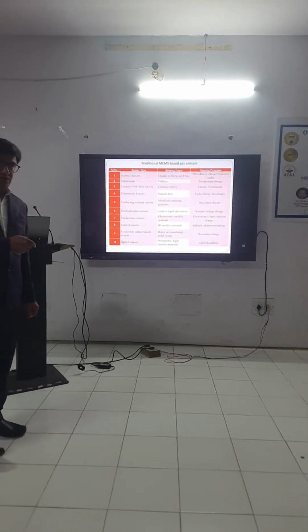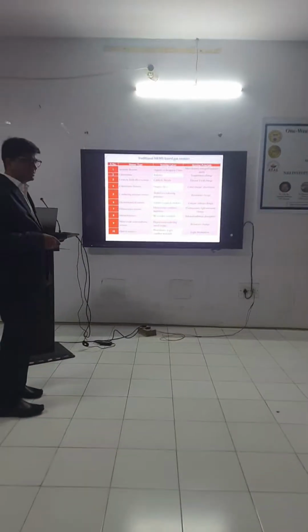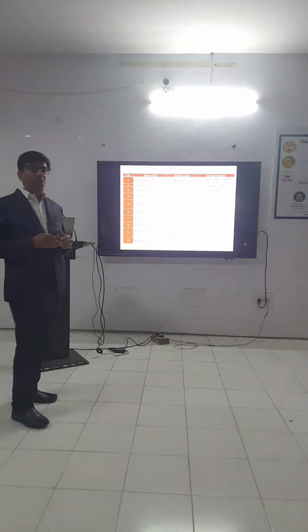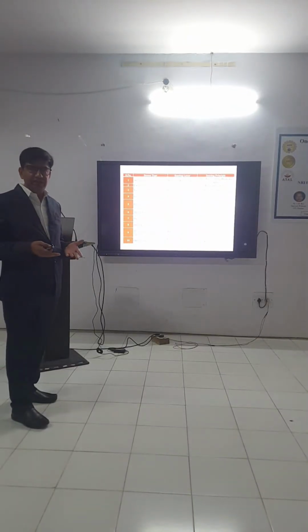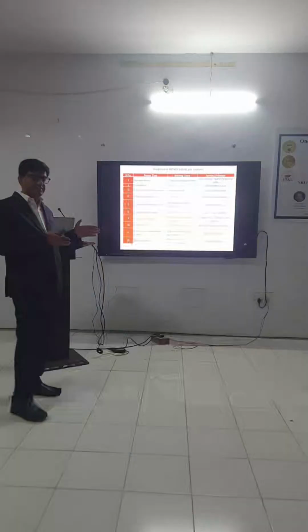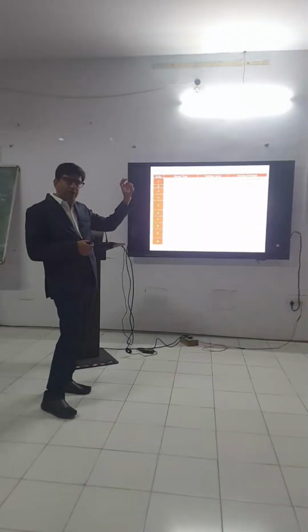will be metal oxide or whatever it is. And inorganic means sometimes you may have a polymer layer. So polymer layer also you have to use for the sensing layer. So there is basically an entirely different phenomenon if you are using an organic layer or if you are using a metal oxide layer as the sensing layer. So in metal oxide, what will be the case?